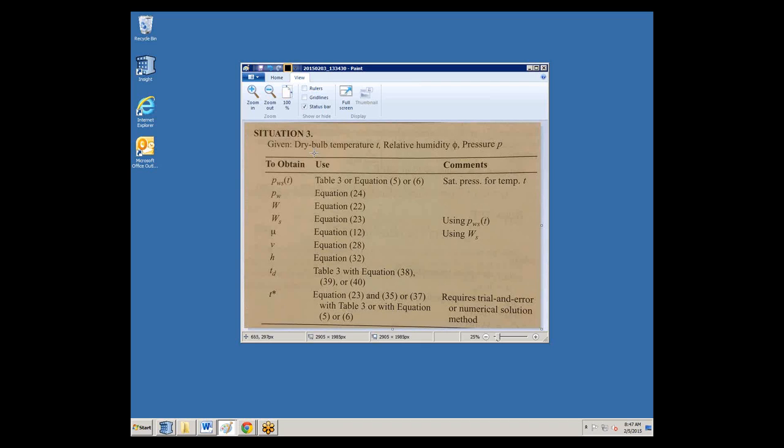What we were looking for was a little bit more accurate formula, because the ones that we had been given by the controls manufacturer were based on kind of a table scenario, and so they didn't approximate certain portions of the curve accurately enough. So sometimes it could be off by a degree or so, wet bulb, and if we're trying to determine whether it's okay to switch into free cooling mode, there can be a lot of hours involved where we wouldn't be able to use free cooling if we didn't have an accurate reading.